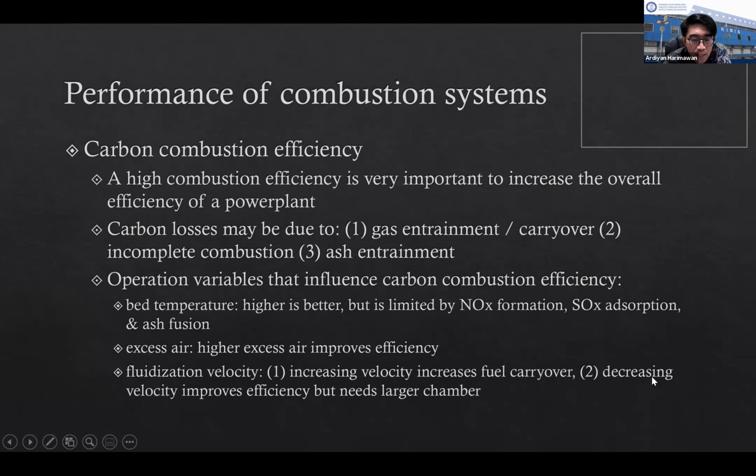And decreasing the velocity will improve the efficiency, because the contact between air and the solid will happen in a better manner, but you need to provide more space. It means you need a larger chamber for the contact to happen, to provide the same amount of heat. Okay.